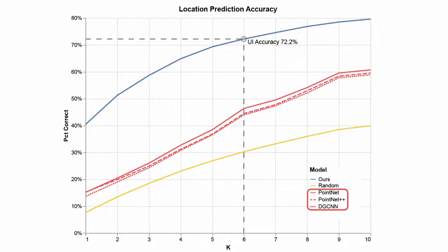And for different kinds of topological entities, there are different reasonable positions and orientations to get position orientations. Like you're connecting the faces on face center, or you're connecting them on the edge center. This is a discrete choice. And reasonable is derived from the B-reps. Yeah, so the reasonable is derived initially from the underlying CAD systems.